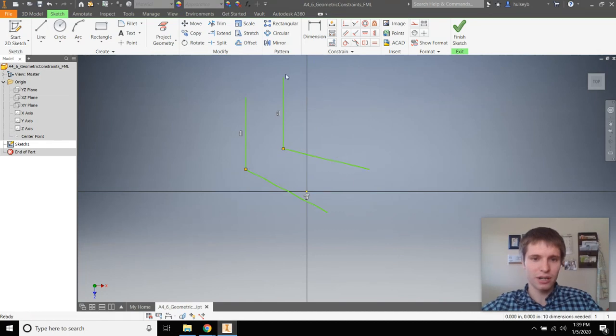And then you can see the kinds of degrees of freedom I have here. I can move this line around, but I can't do that if I select this point. It'll just slide up and down because that line is vertical. The degrees of freedom can be shown by clicking this button here. Unfortunately, there's not a hotkey, but you can see I can go in and out with this line, this curve. I can go curve up and down. I can move all of these points left and right, except for this midpoint here. I can only move that midpoint side to side. That kind of gets messy, so I like to turn that off. But if you're ever interested in what degrees of freedom you have, you can add those there.